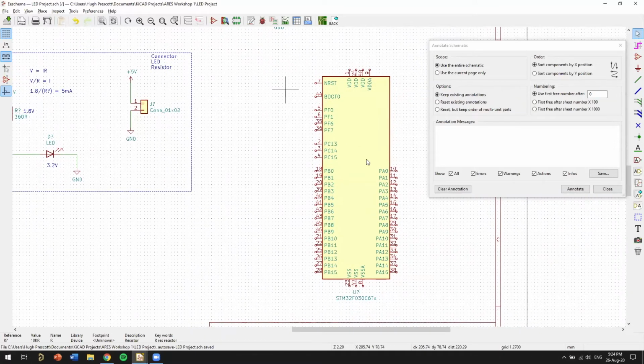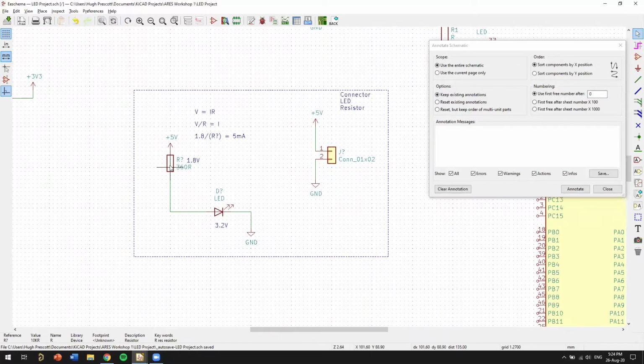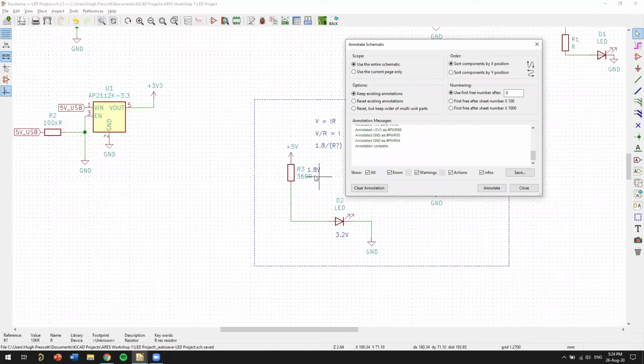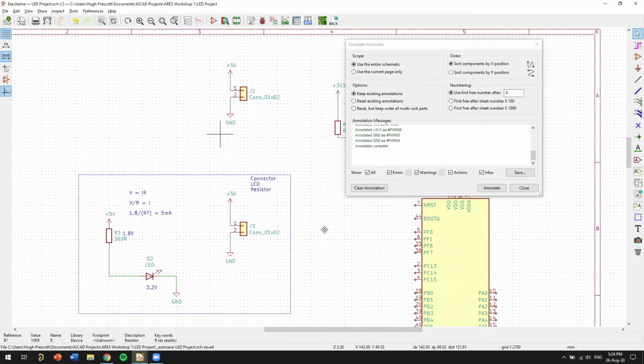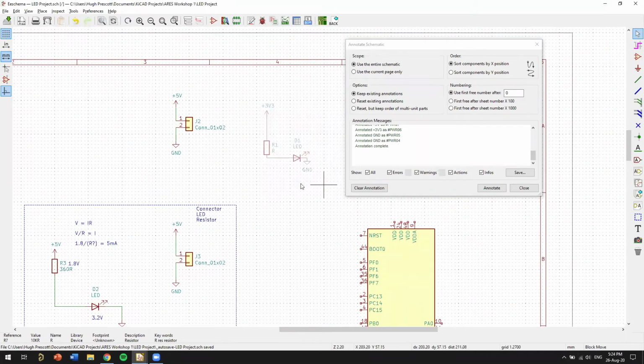And I think transistors are Q question mark. But the point is, you don't want to be numbering all of these yourself. So you can annotate a schematic just like this. Annotation complete. And now you can see that here. So this is pretty messy because I have some other things I want to explain up around the place. Actually, let's delete these.